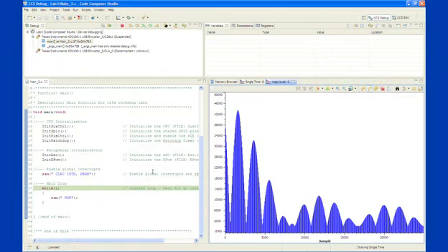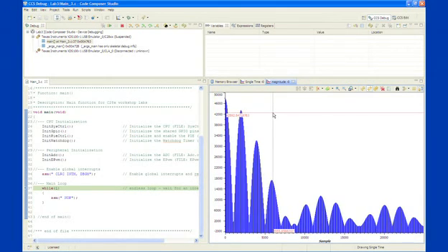And we'll take a look at that, and sure enough, here is our frequency domain plot. I can just left click and hold the mouse down, and we'll notice the peak here. The top number you see is the amplitude, but the bottom number is what I'm reading, and it's at about 2 kilohertz. So that's our frequency domain plot.